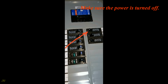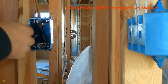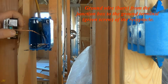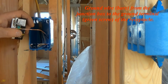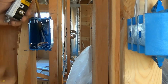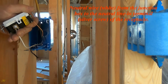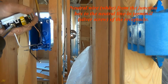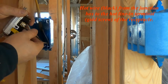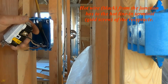Make sure the power is turned off. Connect the GFCI receptacle as follows. Ground wire, bare, from the junction box to the ground terminal, green screw, of the receptacle. Neutral wire, white, from the junction box to the neutral line in terminal, silver screw, of the receptacle. Hot wire, black, from the junction box to the hot line in terminal, gold screw, of the receptacle.